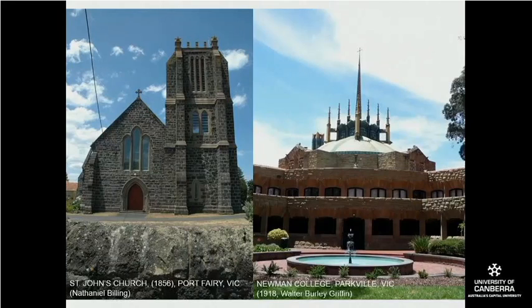Now, stone is good in that it can be relatively waterproof and fireproof. It has very good acoustic damping properties, so it will cut out the sound from outside the building. When you cut it into blocks, it's pretty easy to join with mortars, with old-fashioned and new-fashioned mortars, and it generally weathers well. Now, I might say that in the case of Newman College, this hasn't quite been the case,